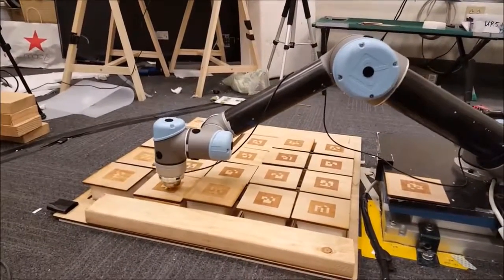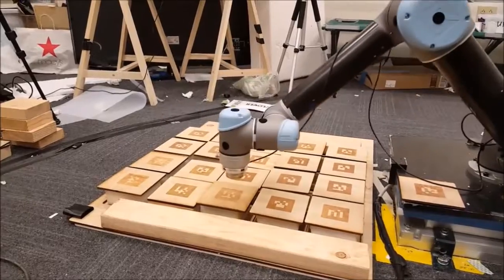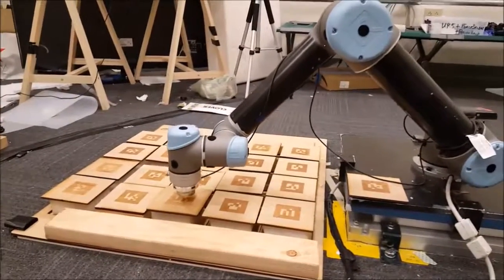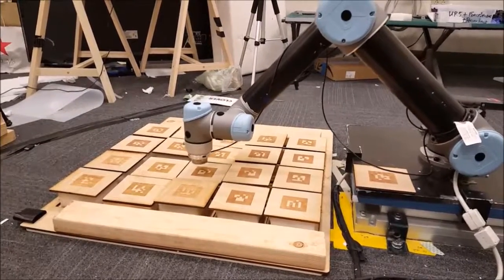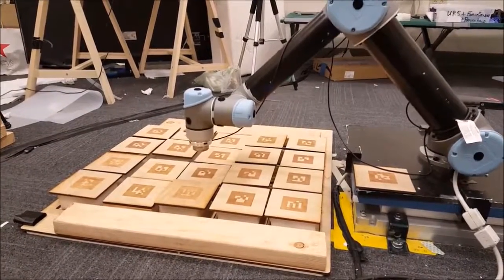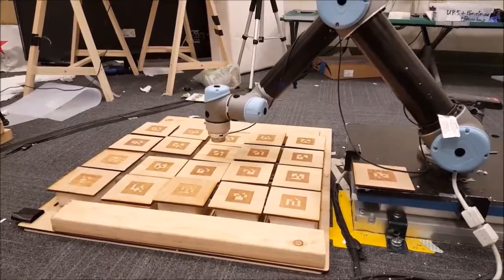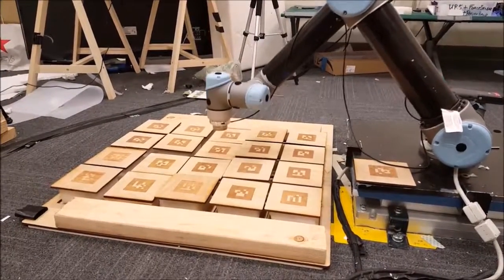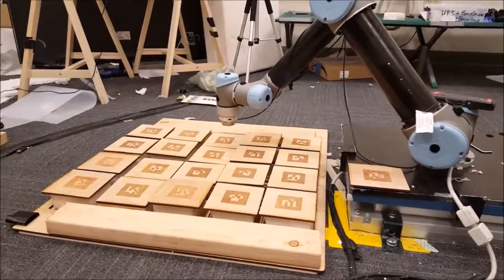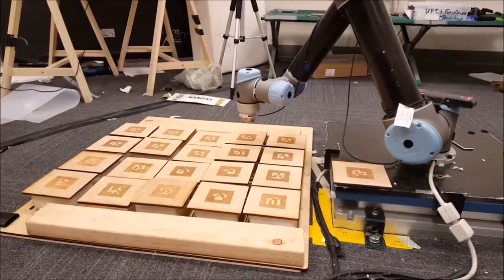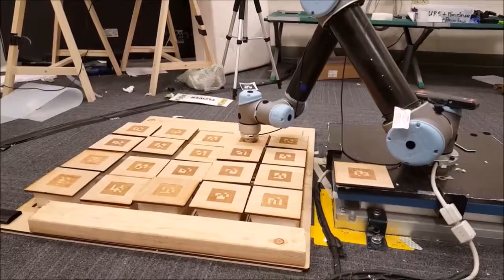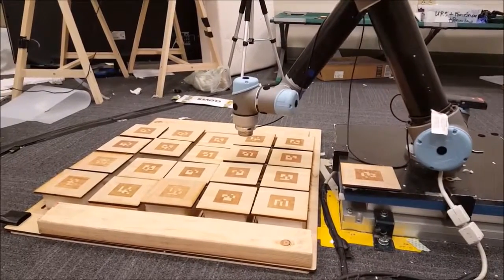The way we are reading the force values is we make sure that the force sensor is calibrated and gone over a certain threshold force, and then after that is reached, we map the slope of force versus time, and by looking at the steepness of the slope, we're able to tell whether or not the block is wood or foam. So as you can see, the UR5 is just traversing the grid in a snake-like motion.